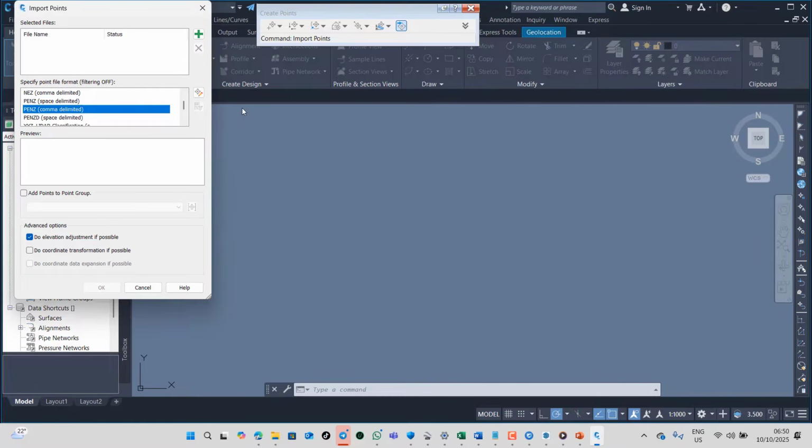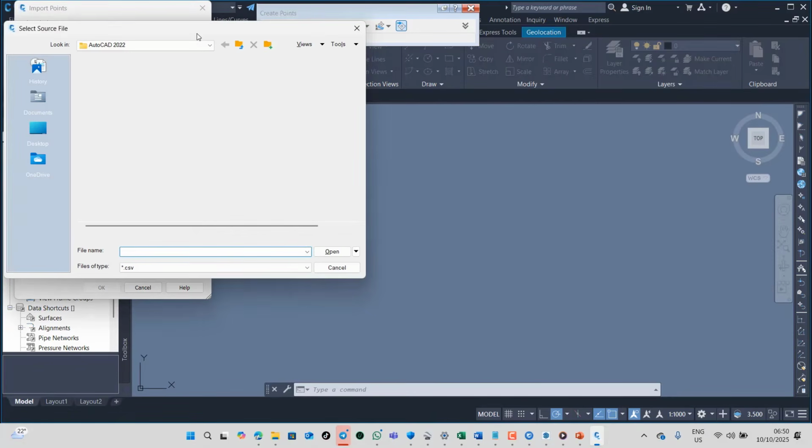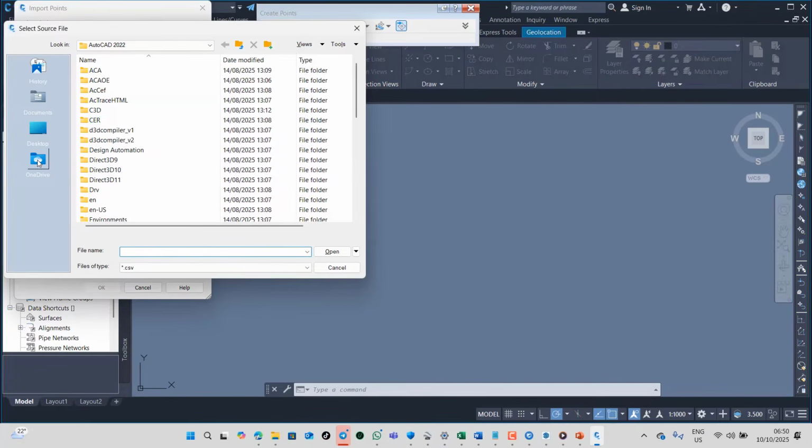It's because we are just doing this as a training, so there may be no need for it; we can omit that, or we can be excused by that. And I said obviously that you only use this whenever you are just doing a presentation kind of drawing, but for a real life project, by the time you want to do a real design, you have to visit the site and take up those points, and then make sure your surveyor adds a description to those points. Very, very important. So if we are done with that, I can just click on this plus sign here.